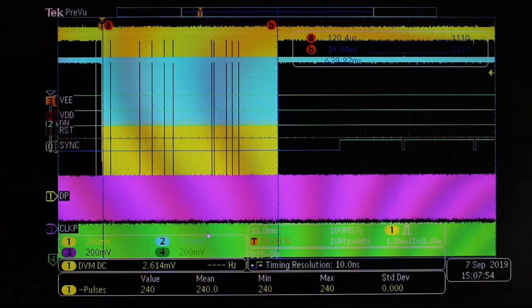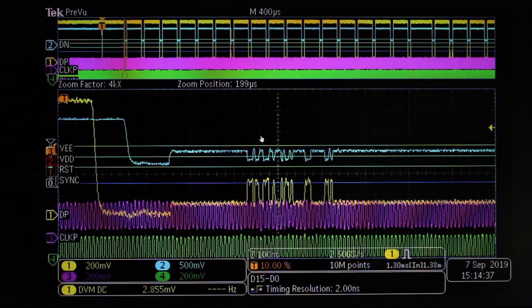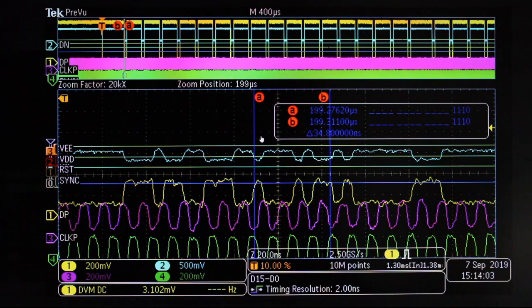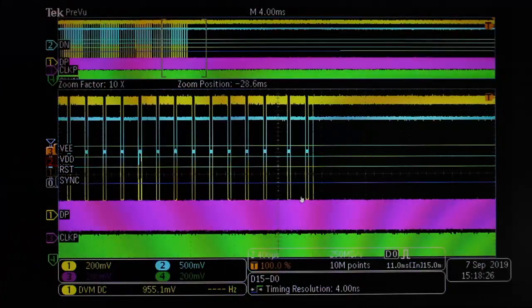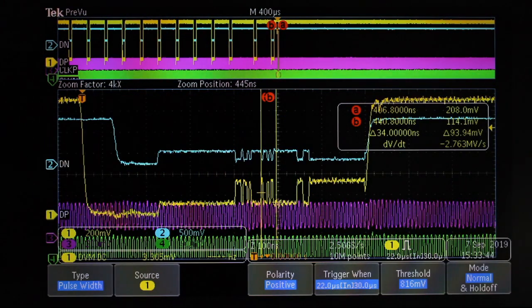Let's go further. This is how the complete clearing sequence looks. There are multiple single write commands here. This is the first line. This is a zoomed in view of the first line. This is B8 39 and so on. This is the end of the clearing sequence. In the end of the clearing sequence, iPod also sends some extra commands, which is 05 29 00.